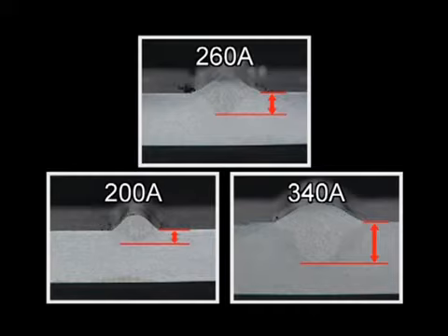Since the welding amperage is a major factor of the amount of penetration, welding amperage is adjusted based on the thickness of the plate to be welded.